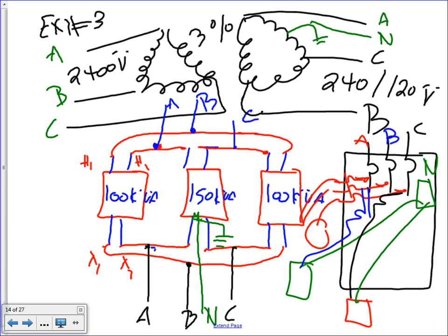So if this is a delta, they call it a delta 6 or 10 panel. When you're looking at this panel, you will see a circuit breaker here, space, nothing here, and another circuit breaker. Then circuit breaker, space, circuit breaker, space, circuit breaker. That space is just a cover like this. This will indicate to you that that's phase B, you can't use it, unless you're doing a three-phase.